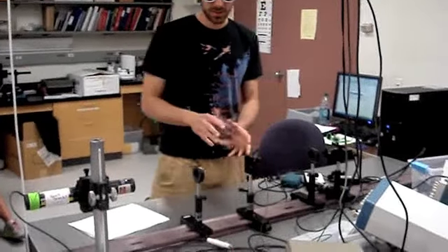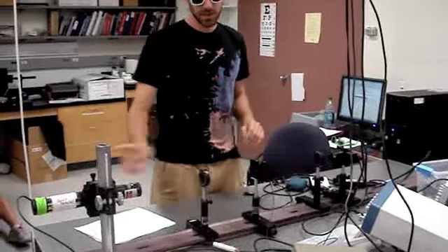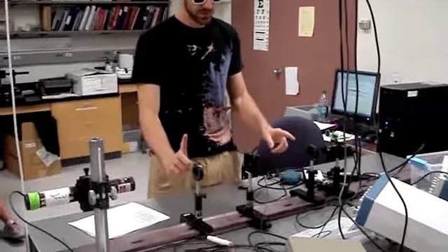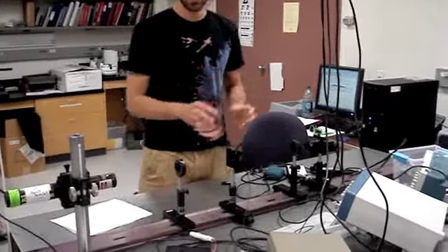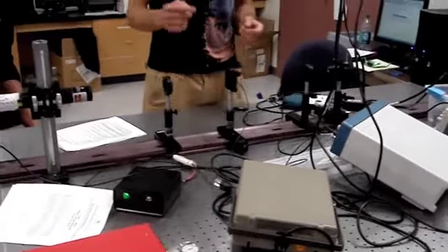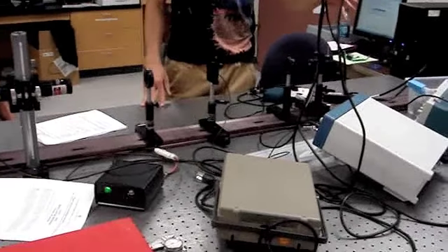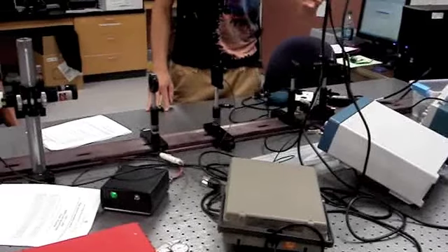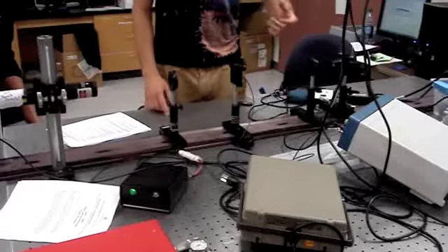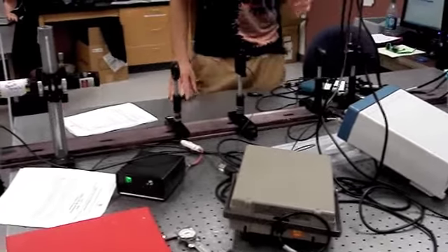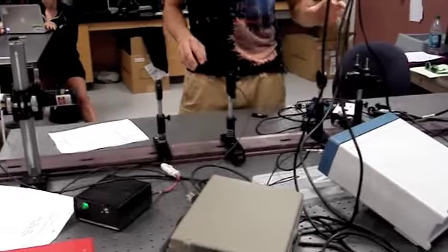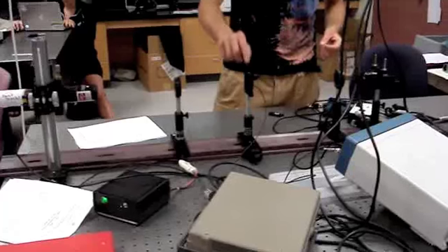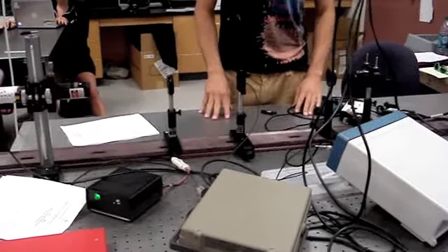We used our liquid crystal cell to create an intensity modulator. We have a laser coming in, and then a system with cross polarizers, and we put our cell in between that will retard the beam depending on the input voltage. We changed our input voltage from 1 to 9 volts peak to peak and read the output transmission, and from that we plotted how the voltage affects the transmission of the system. For the next part, we chose the maximum transmission voltage and used that, and then rotated our axis of the cell to see how that changed the system.